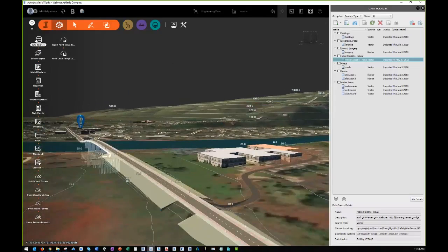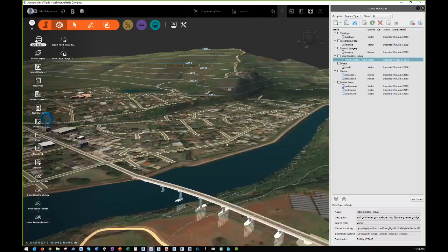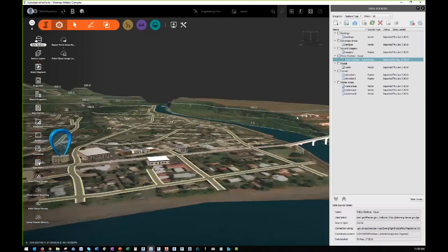You are not limited to just materials like grass or sand or dirt or brick. You can use colors as well, or ground coverages that you've specified there to color code these areas of cut and fill in your project. So InfraWorks 2020, big features and enhancements there: your ability to do that BIM 360 or local model save option, your save back to ArcGIS Online for the geometry, and then we also have the structure edits in spreadsheets.